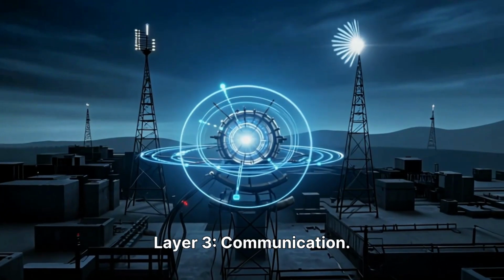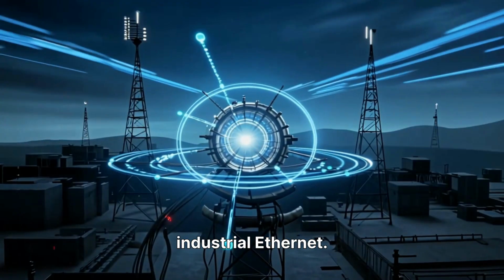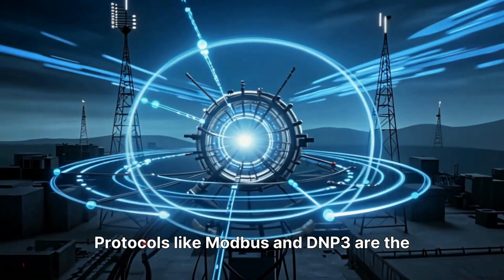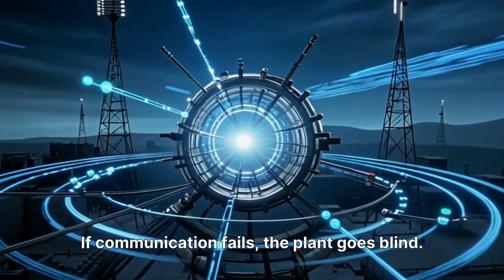Layer 3. Communication. SCADA transfers data via fiber, radio, or industrial Ethernet. Protocols like Modbus and DNP3 are the languages machines use. If communication fails, the plant goes blind.